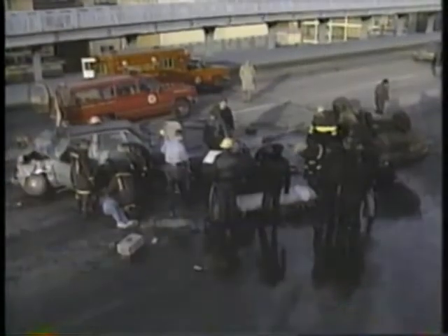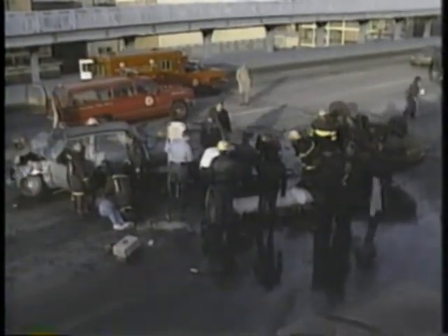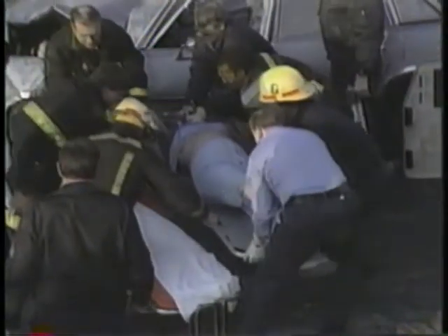This means that in a frontal collision, after the front of the vehicle decelerates, the occupants will continue to move forward. Very quickly, the rest of the vehicle structure also decelerates, and within 40 milliseconds, the occupants are beginning to leave their seats. Since they have only the space between them and the inside of the vehicle to travel for deceleration, they too will soon stop when they contact the car's interior. If this deceleration is too rapid, the forces on the occupants' bodies can be severe enough to cause serious injury or death. This is referred to as the second crash, the point after the vehicle crash where occupants collide with the car's interior.